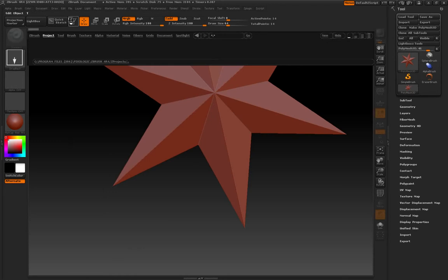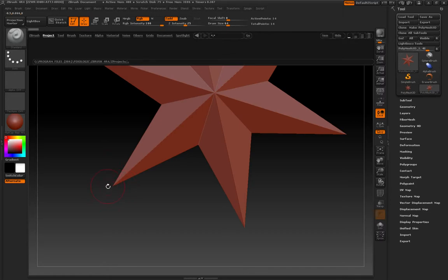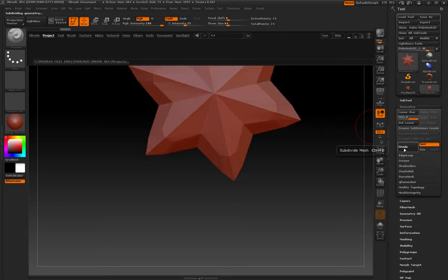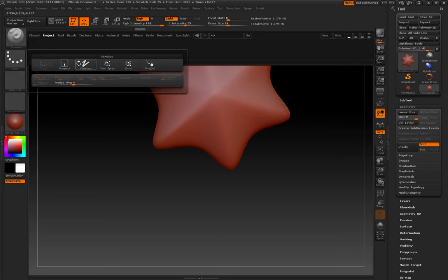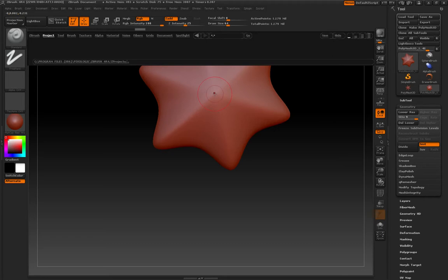So we'll go ahead and undo it and create a new one. Now we'll go into edit mode, and you can only move the vertexes which already exist. So you can't really do much with this right now because there aren't many vertexes. So I'll just go right ahead: geometry, divide, divide, divide, divide, divide, divide, divide. It's always better to stay in a low resolution when you start off, and then move up when you get to the more detailed sections.